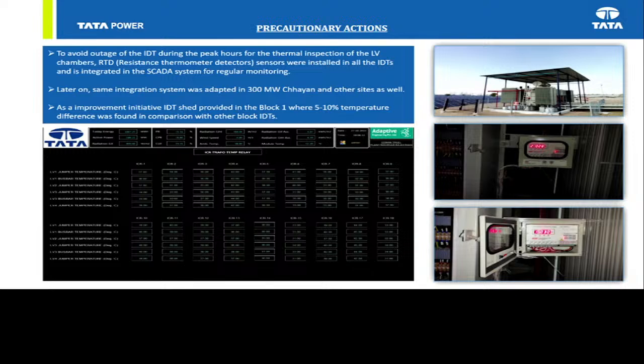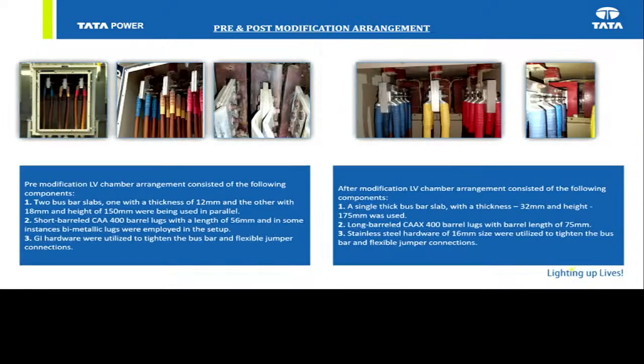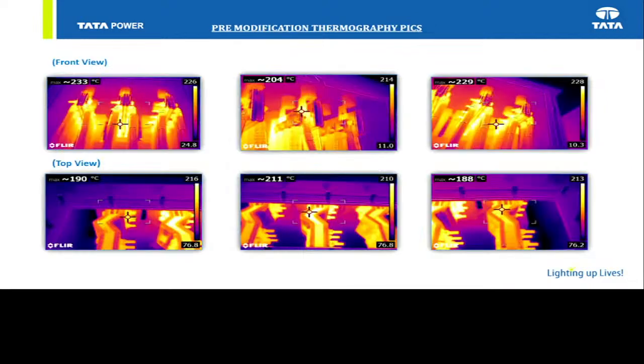This is the cleaning. Actually there was a lot of dirt and rust, so that was also causing the heat. And later on, we were not sure, because one more piece of information I would like to give: this is the first time we were using an aluminum winding transformer. That was not new, but this was the first time at this location an aluminum bus bar was used. Most OEMs supply a copper bus bar for the current collector at this location, but this was the first time we used an aluminum bus bar. Because of that, we were not sure whether it would sustain in the summer season or not.